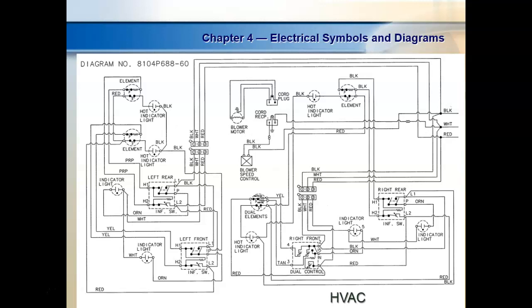Notice these are all different devices, right? What we have to understand is that this looks like a wiring diagram, and we'll talk about the difference. A wiring diagram tries to show how things are associated with each other. So when I see these little dashed lines around it, it means all this is inside one unit. A schematic doesn't care. A schematic draws things according to logic, how it works, and it doesn't try to give you an idea of what's inside the same units, right? Does that make sense?